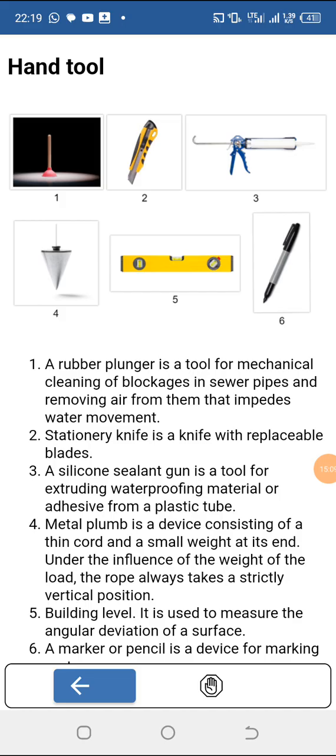Number one, cleaning the tool. Number two, wiping, removing maybe the dust, removing the corrosion or maybe rust. Sometimes with metal tools, we advise to use oil. You wipe oil on the screws, you use oil in the jaw of the pipe wrenches.